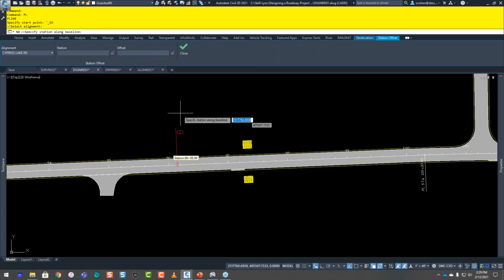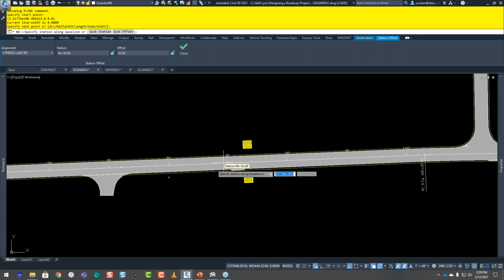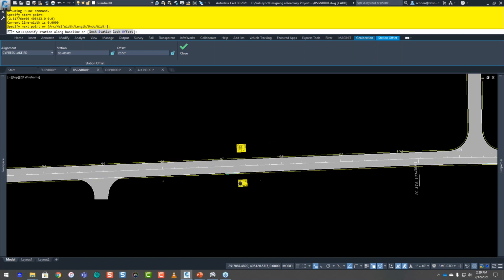Now, with this new ribbon in 2019.2, as long as you're using that or above, you get these little fields to enter here. You can use them. I'll do it for the right side here. If I type in here 9600, you press enter, you don't press tab. Then you click over here. I want to, let's say, be 20.5. Notice how it shows you the point that you're at, and then notice how it keeps continuing.